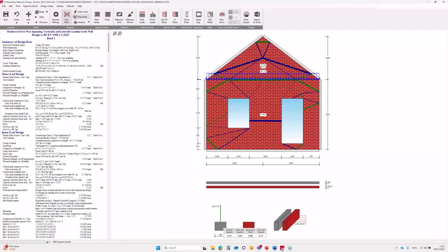As we can see, the software allows us to model non-standard complex walls as a single unit, automatically divide them into analysis zones, and carry out the realistic yield line analysis. This gives us a clear and straightforward indication of which part of the wall is failing and how we can effectively strengthen it.